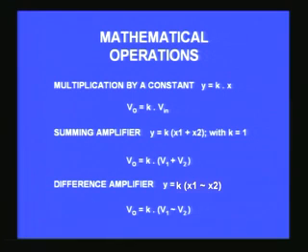So I just want to show you a couple of slides which we have seen already in some of the previous lectures about the various mathematical operations that can be performed using an operational amplifier. Like for example, on the screen you can see multiplication by a constant, where the output is some constant multiplication of the input, then a summing amplifier where the output is the sum of the two inputs with a constant factor if you want, and then difference amplifier where the output voltage is proportional to the difference in the two